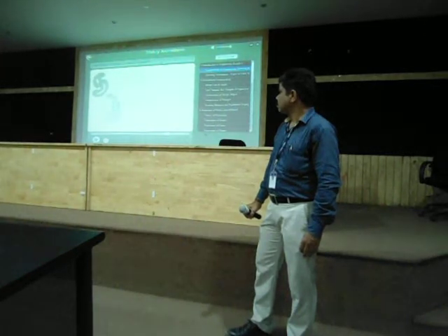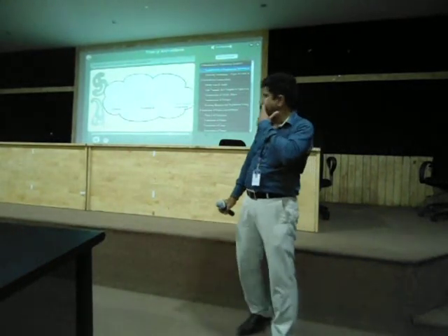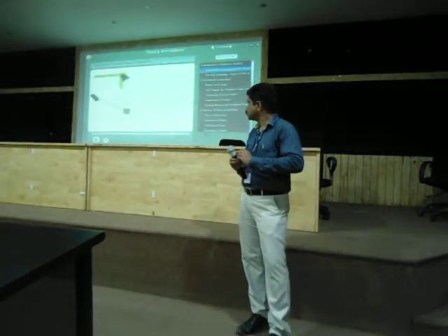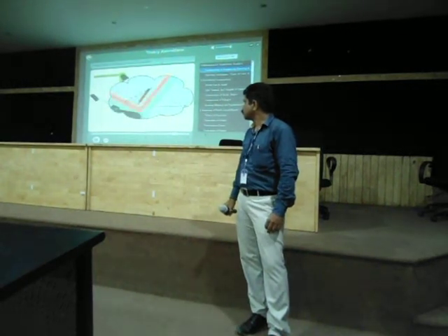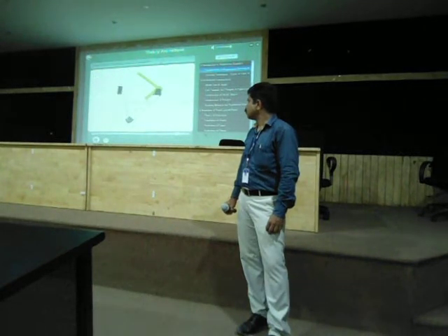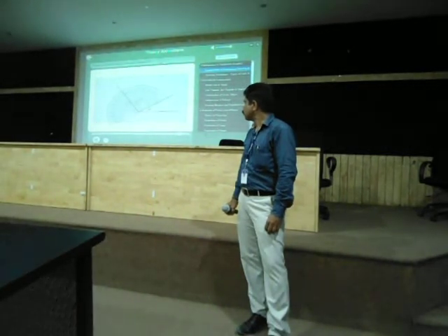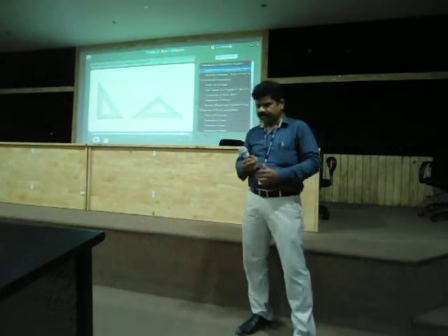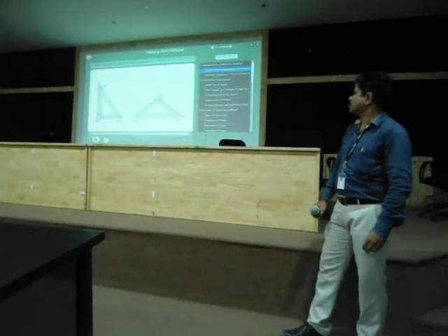Another interesting tool is French curves. They are used to draw irregular curves such as ellipses, parabolas, hyperbolas, and the like. The drafter is a very useful tool for drawing parallel lines at any given inclination. It has a scale as well as protractor inbuilt. Looks like a robot, isn't it? Protractor is used to measure and lay out angles. Another tool is set squares, also known as triangles. They come in flavors of 30, 60, 90 degrees and 45, 45, 90 degrees.